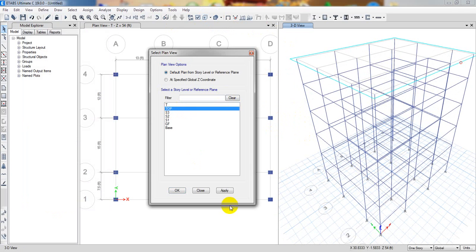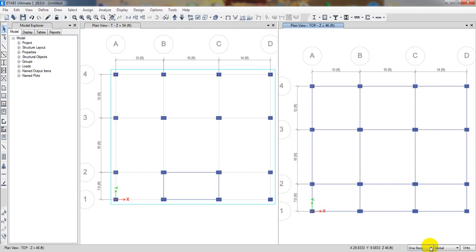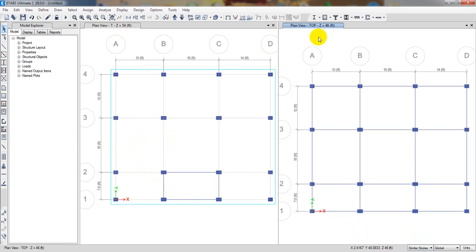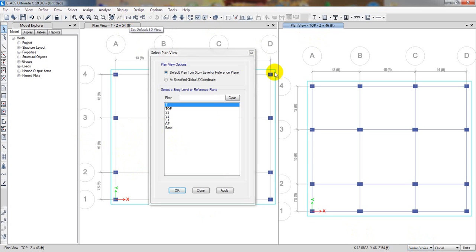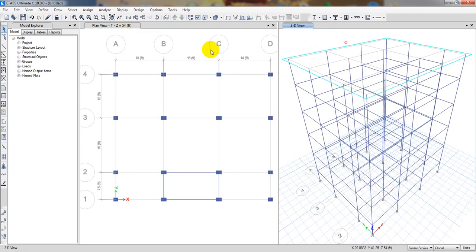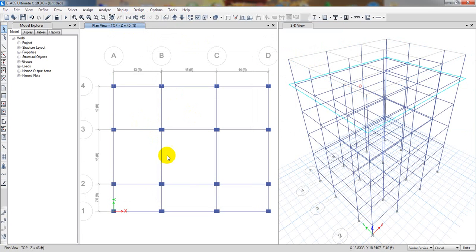Now I'll go to the top floor, I mean where we'll use similar Storey, and I'll give okay, and here on Storey, I'll select similar Storey. Okay, from here I'll select similar Storey. Now, sorry, I'll close that, that will be in 3D, but that section will be in top. Then apply. Now we'll draw our slab here.